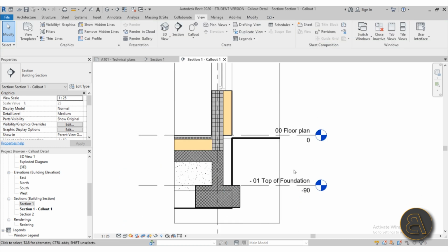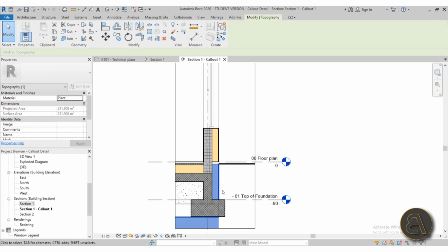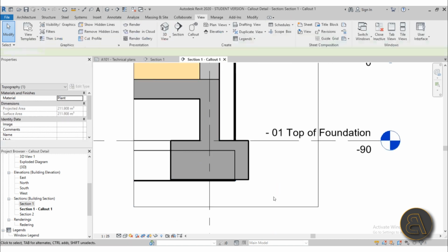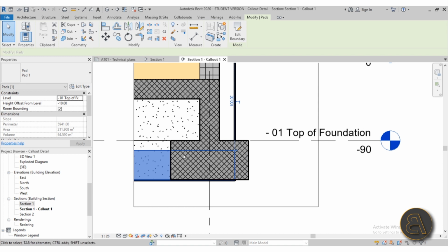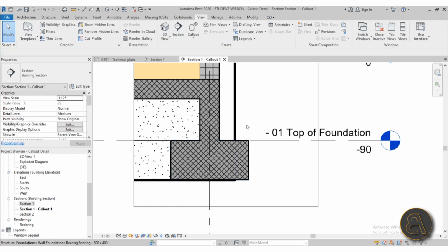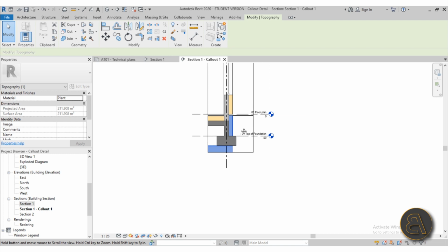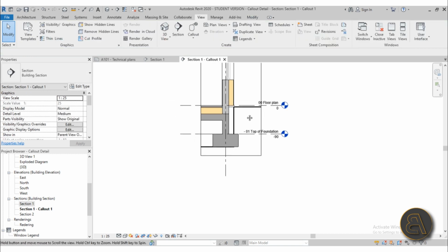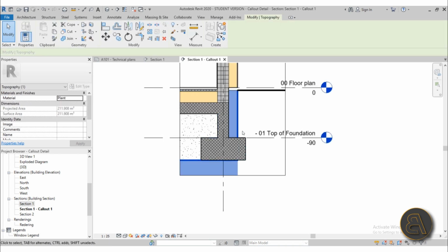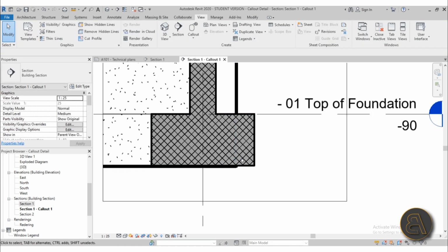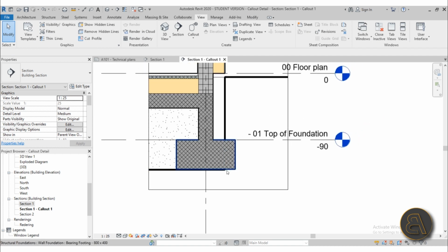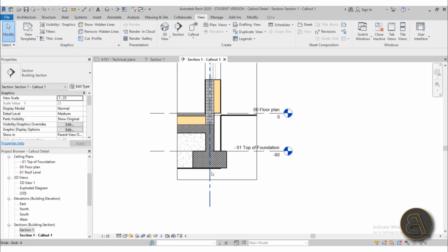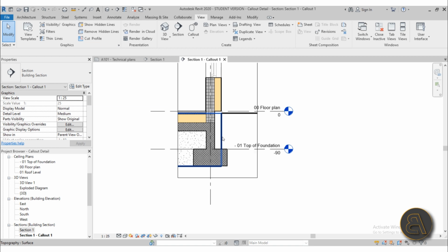Now here we can start playing around with some modifications. So for example, this topography, or actually this is a building pad. This kind of looks weird, so I can hide that in this view, and now it looks a little bit better. But here, once we went into the detail view, you can see that this building pad doesn't include the whole foundation, and usually it should, just because when you're digging into the ground you would dig up to this point at least. So here we went into the callout and we found out that we have a problem with the original design.